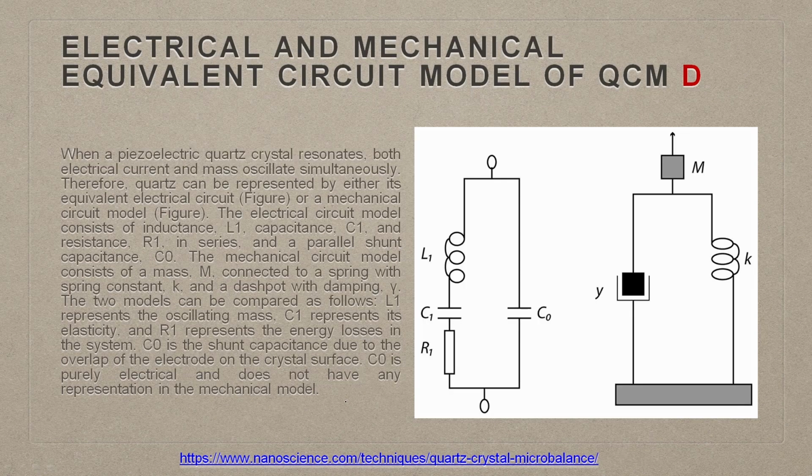Following this, there are two ways you can define this QCM-D. It could be defined either by the equivalent circuit model or by the mechanical model. If you define it by the mechanical model, this is where the mass we are seeing comes in. When a piezoelectric quartz crystal resonates, both electrical current and the mass oscillate simultaneously.